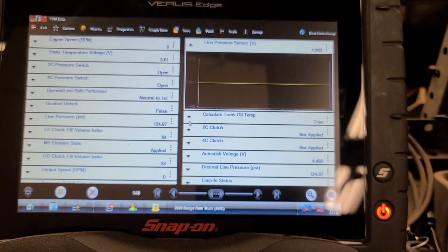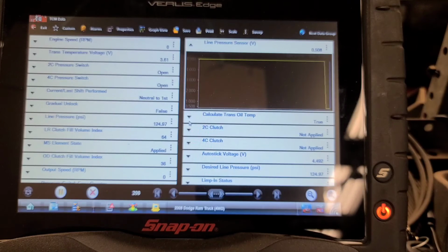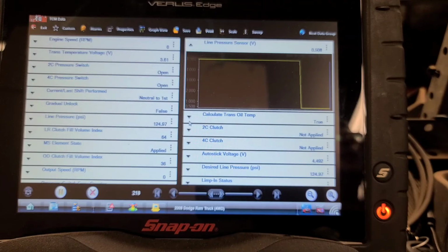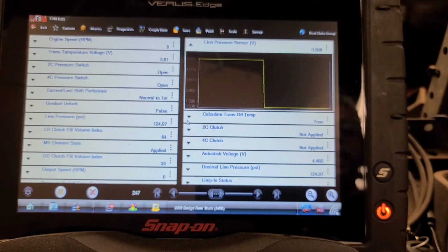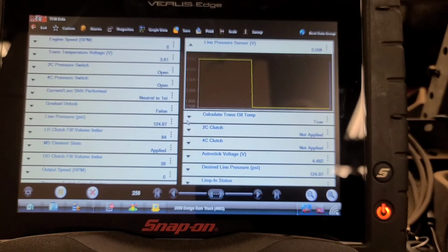So I'm just going to go underneath the truck and plug it in. It's unplugged. Now it's plugged in. That's better. As I was reading in the literature, it said it should be about 0.5 with obviously no pressure on the sensor. So we're going to install this sensor and clear the fault codes out of the system and see how the transmission works. Hopefully that's all there is, because there could certainly be more problems than this.